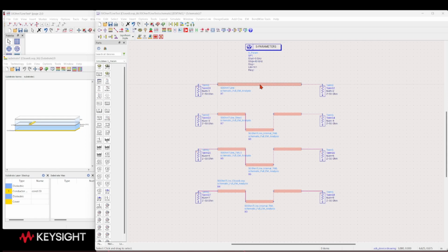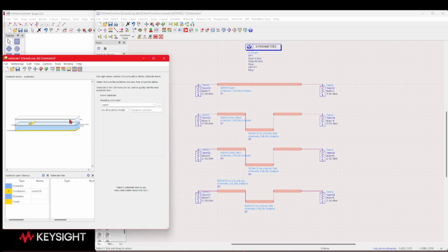And I'm using an alumina 10 mil substrate here, set up in a way that excludes conductive losses, so that we can actually see the effect of the parasitics, and it's not hidden, at least partially, by the resistive losses of the conductors.